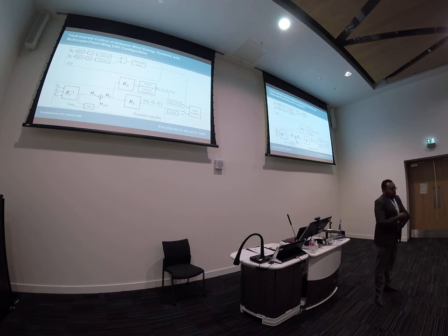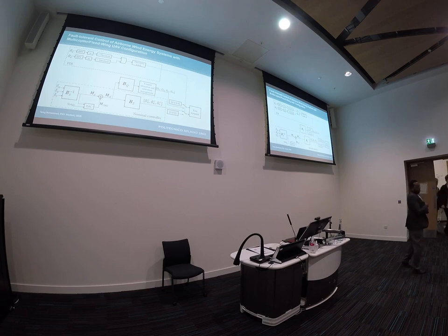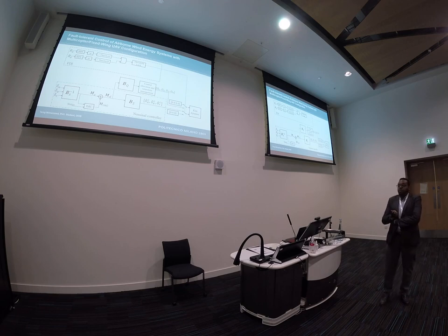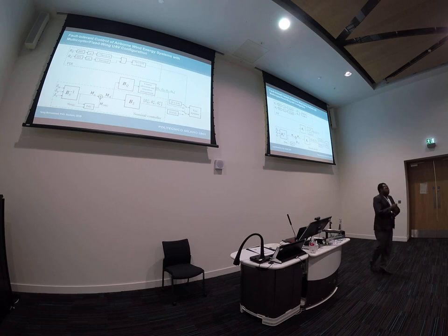Since the low-level controller is built based on a linear controller, and it is not taking into account the tether effect and other disturbance, we also find it more useful to include internal model control here. When we get the output from the internal model control and add it to the moment coming from the discrete surface, we obtain the desired moment. So this is the desired moment to keep the kite looping, flying.